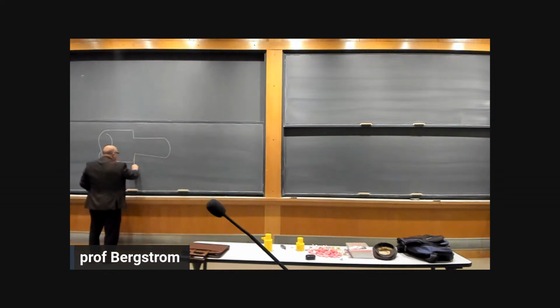All right, so where we ended up last time, we were talking about this idealized turning operation. You can draw it a couple of ways on the board here. We have our bar stock here. We're holding it, spinning it in this direction. We've got a tool here, and we're feeding the tool in this direction. Everybody follows me? This is what we had. When we feed the tool in this direction, it actually makes these little bumps and little valleys on the surface.